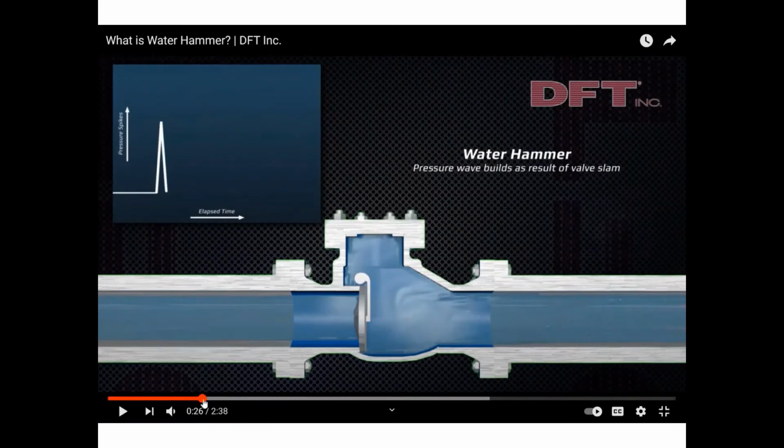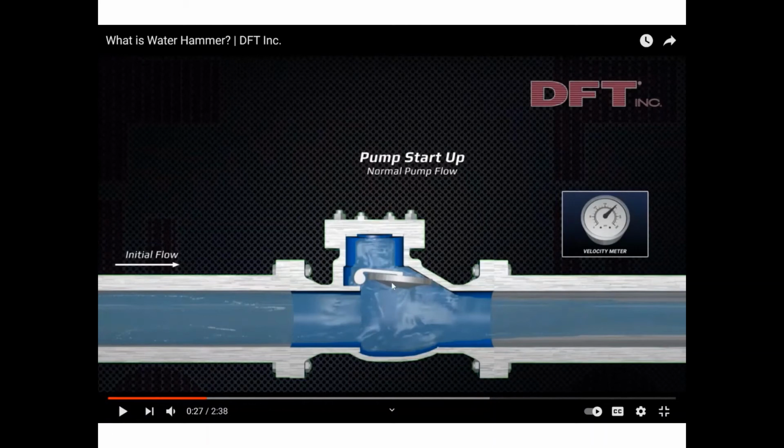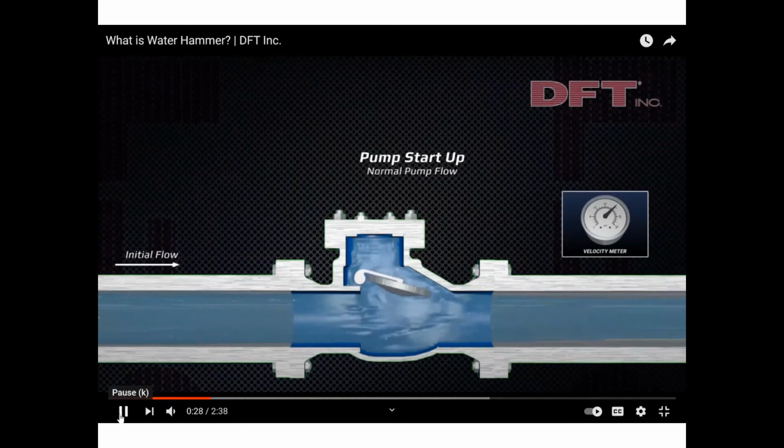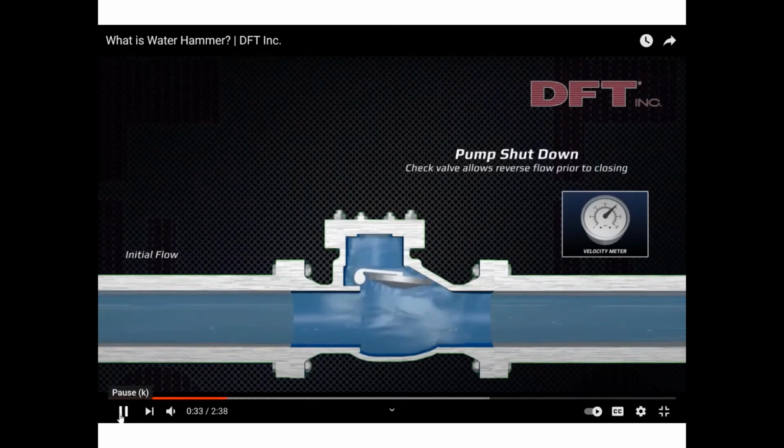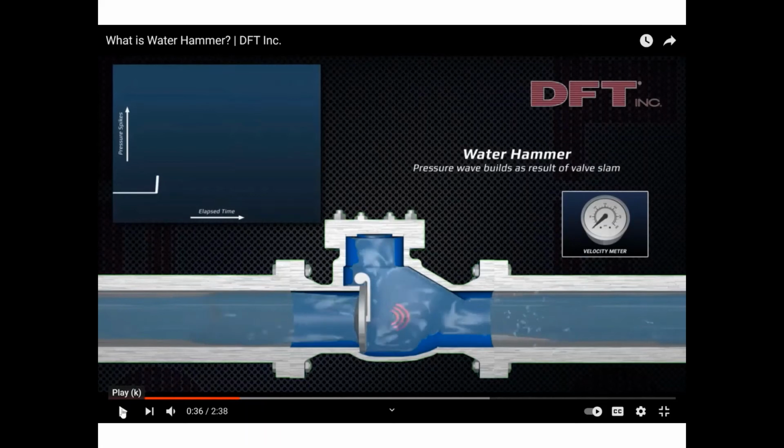So guys, can you watch this again? We have a valve that is opened, so we have flow in the pipe. That's fine. Motion and slamming of the swing check can cause damage to sealing surfaces and fatigue. And if you decide to close this valve suddenly, see what will happen on the right hand side. When the pump shuts, can you see? This sudden closing will cause waves of flow here.